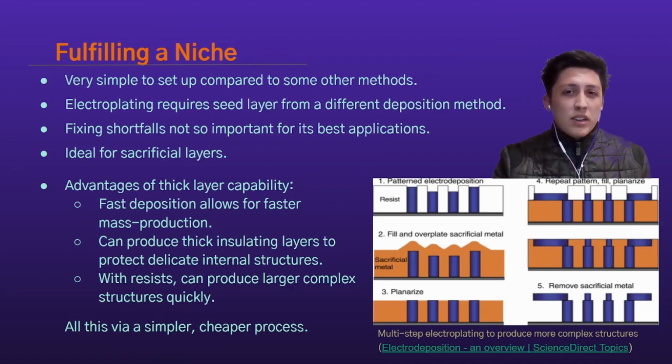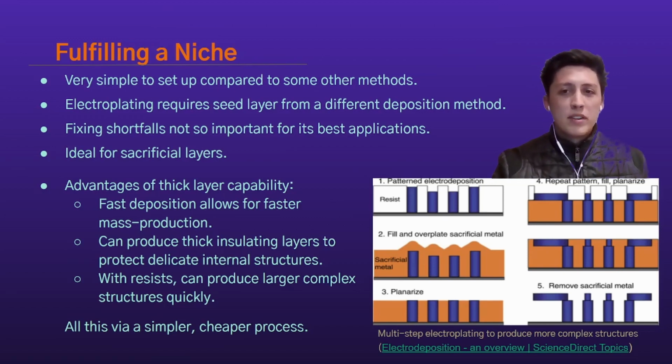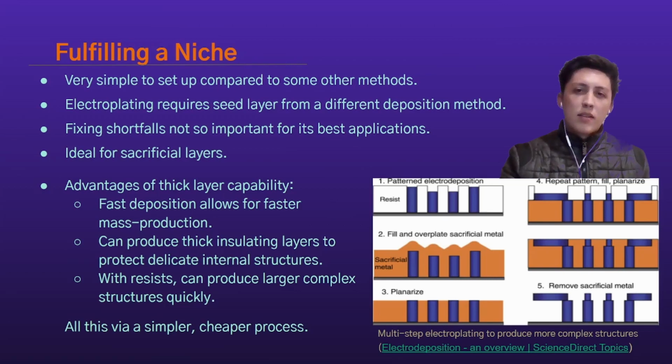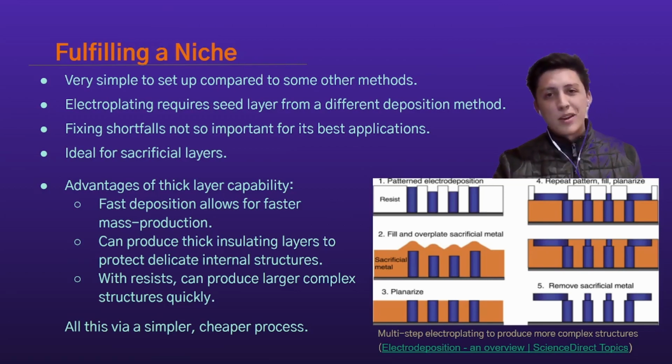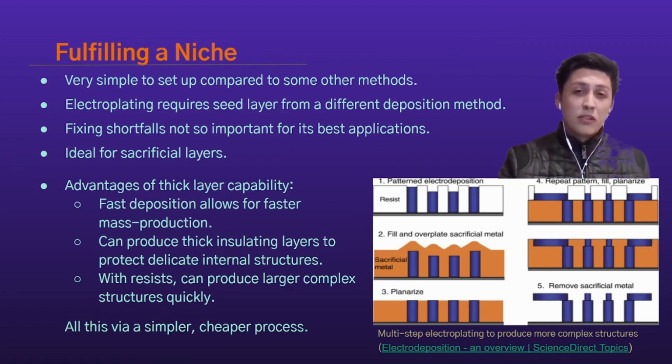Electrodeposition may fit well into a niche use case alongside other methods, as it's comparatively good at applying thick metal layers or more bulky metallic components of microscale devices, while remaining a less technologically advanced and prohibitive process. These benefits are likely part of the reason for electrodeposition's increasingly widespread use in micro and nano manufacturing. When considering process flows holistically, choosing electrodeposition where applicable can allow for a simpler, faster, and less costly production.